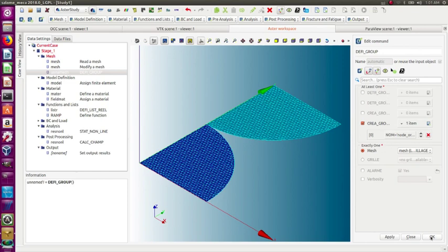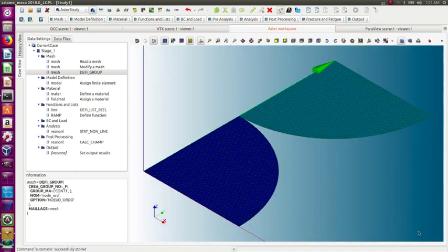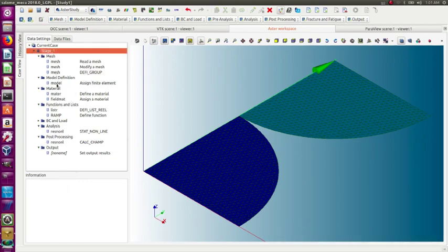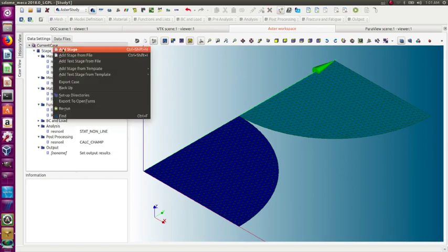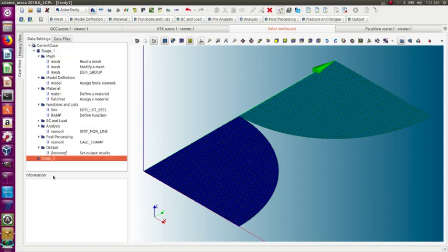Okay, that's it. So this group will be used in order to extract the curvilinear coordinate from this. Now I'll do something which is actually quite good in Aster Study. Maybe you don't know about it. You can set several stages to uncouple your different analyses, so you don't have to run all of that every time if you want to do some post-processing afterwards. So for that, create a new stage, and I'll set up my functions in this new stage. So you'll see afterwards. Basically for the moment I'm just adding a new stage, and what I need to do here is